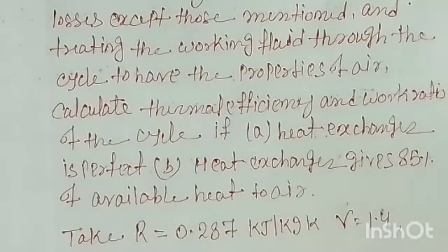So first of all, the thermal efficiency you know very well, right? The thermal efficiency is the net work by heat supplied. Net work means the difference between the work produced by the turbine and the compressor work. As well, we have to find the heat supplied. The output is the net work and the heat supplied is the input. So for that we need to know the temperature at the end points.